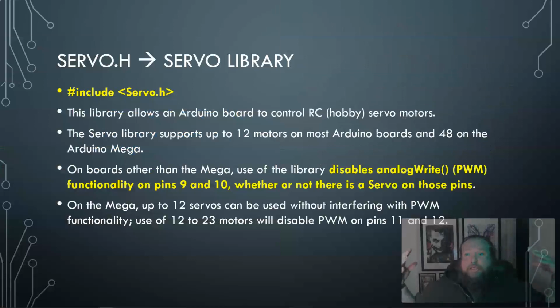Okay, getting into Arduino specifically as a way to control these servos, because there are other ways, but if we're doing this, we're generally going to be using the servo library that's built into the Arduino language itself and handles things for you. I'll be explaining this more here. This is some of the syntax of how to include a library that's built in, like you're importing. So it brings up, but this is the first step of understanding that you need to look deeper than just copying the code, understand that there's limitations in there.